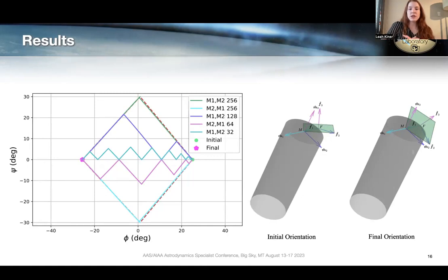So for example, during the initial period of actuation, for the same motor steps, the gimbal angles vary a lot less than when the gimbal is closer to the central portion of this diamond shape.